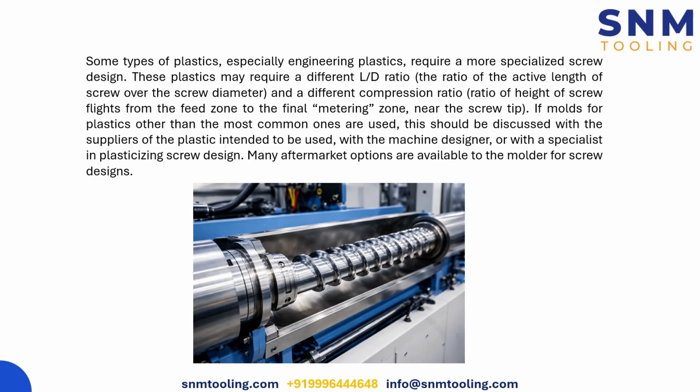So, for example, if we have an abrasive material like glass filled nylon or mineral filled nylon, we need a wear resistant screw. And for heat sensitive materials like PVC or PET, polyvinyl chloride or polyethylene terephthalate, we require low shear designs because the more the shear, the more heat is generated, and this can lead to plastic degradation.